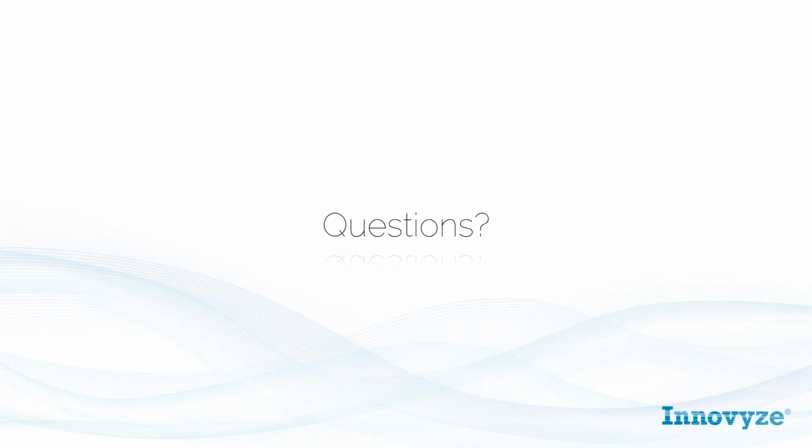And the second question is for Matt. Do you always use the GIM in all of your calibrations? Yes, we do. Yep, absolutely. So from the start of when you've measured data, you don't even start your calibration without actually considering those parameters? We'll probably set some default parameters first, and there's a hierarchy of how we move through the calibration process. We do start with those high-level contributing catchment areas, and the GIM is probably the last thing that you're tweaking, but it's certainly in there from the start.